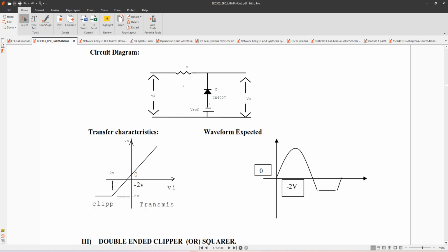The diode is connected opposite now, but we connected the CRO plus here, minus here only. So we are measuring output plus here, minus here. Here we got the diode positive here, negative here. So here negative, this is positive. So minus 0.6 is there. Here you have to add minus 1.4. So for minus 1.4, negative is this side. Okay, negative is this side.